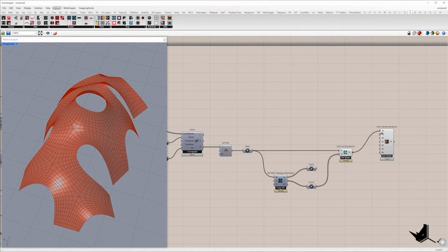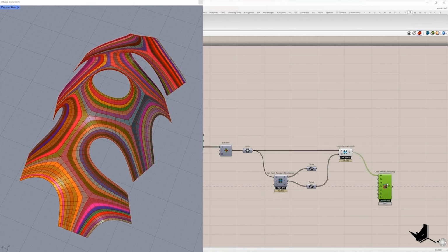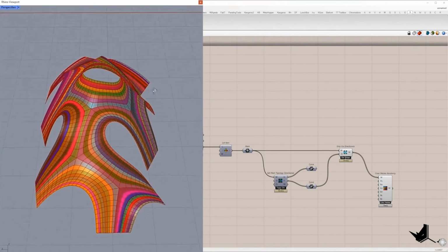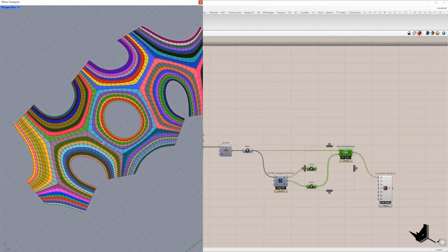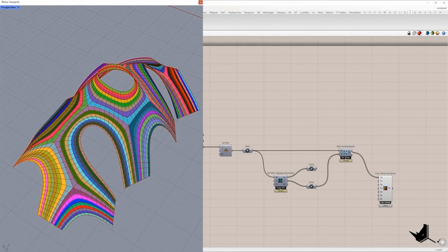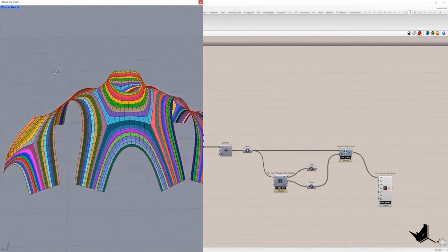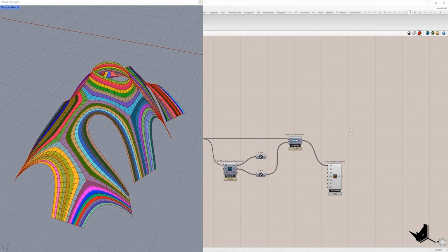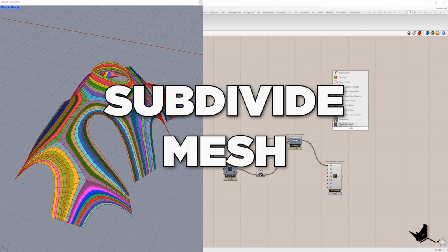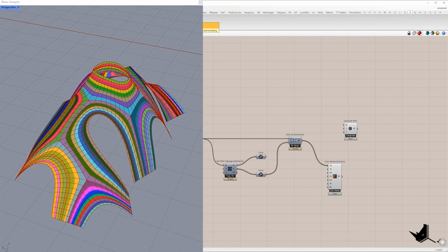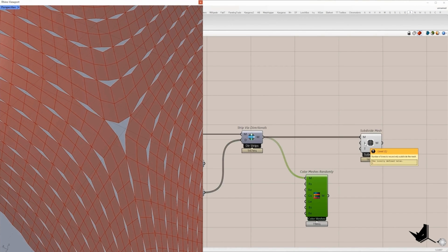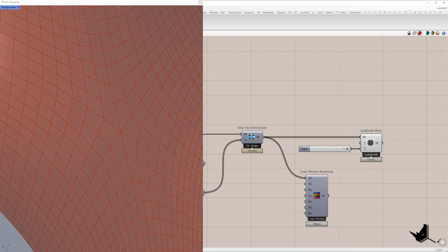I will turn this off just to visualize these stripes. You can see how the mesh is separated. So we get here, let me check, 80 stripes from a single mesh. All right, in the next step, I'm going to subdivide this mesh, also with the Stripper plugin. Here we should place one level of subdivision, and the type should be 1 instead of 0. I want to keep fixed naked edges.